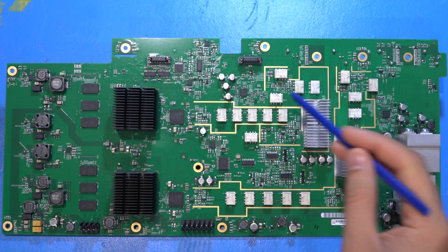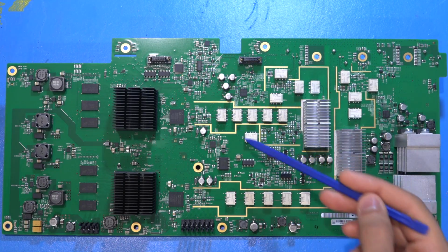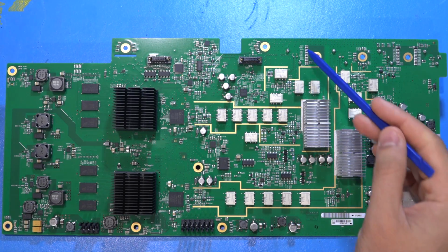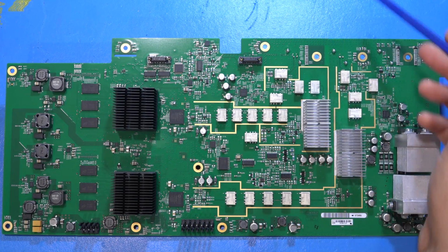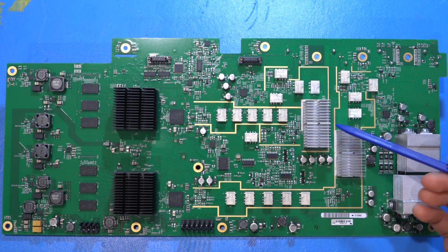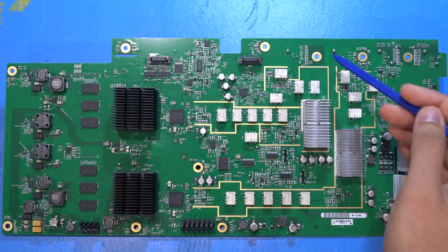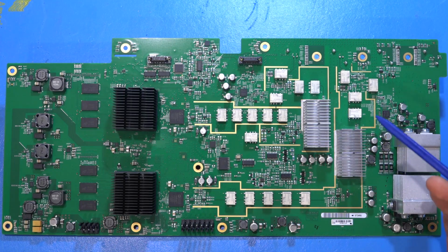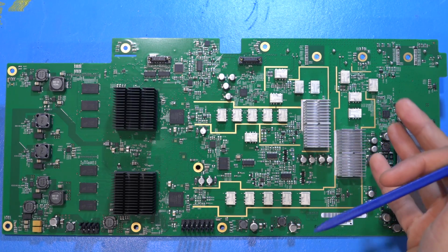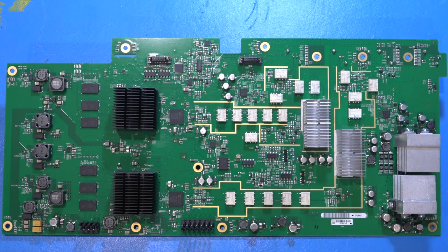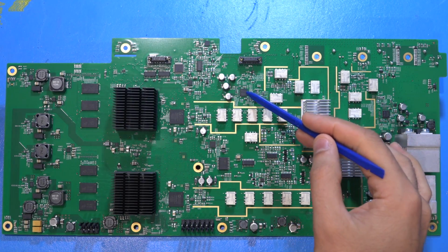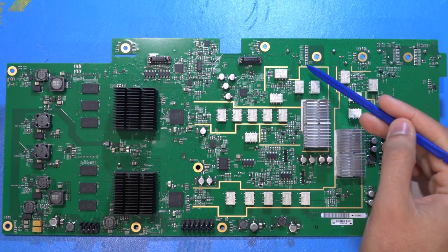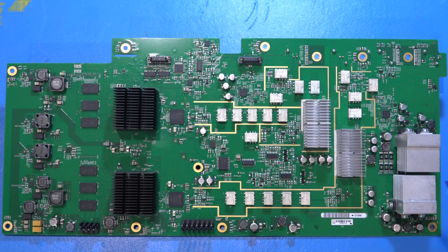The reason I think it might be their own ASIC is because, remember, this instrument gives us InstaView, which is a direct representation of the output signal being applied to the ports so that you can see if you have any mismatches in the impedance, so you can monitor your own waveform. That means that you need to somehow get the signal from the output, sample it, digitize it, and display it. So you kind of have a mini 2-channel oscilloscope built into this instrument at the same time as an arbitrary waveform generator. So I think that these might be the front end of those sampling devices in order for you to be able to look at that signal and condition it so that it can be digitized.